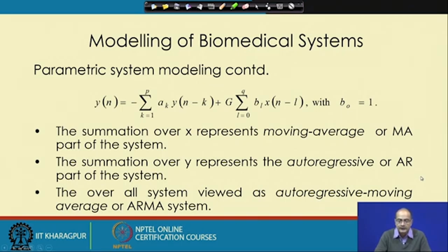One part of it is the physical model. For example, in the vocoder model, we have seen different kinds of input, sometimes the glottal pulse, sometimes the turbulent air coming through from the lung. That turbulent air can be modeled as white noise. Those are the physical significances, but there is a mathematical significance also: in both cases, if we look at the autocorrelation functions, the autocorrelation function is an impulse, and that gives rise to